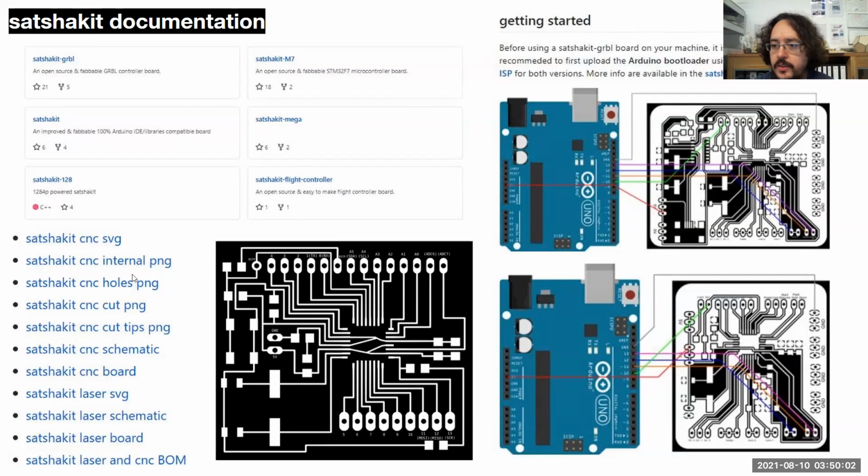But at that time, you know, there was just maybe the Eagle file. So what I brought was a complete pinout and the layout of the boards, the complete files, the complete instructions on how to connect things, and the step-by-step instructions on how to program them, how to use everything, and so on. So in this case, one of the difficulties we had was the conversion between the low-level pinouts, for example, the ports of the microcontroller, and the pinout of the Arduino bootloader, where you have, for example, the numbers of the Arduino libraries. And this always caused a lot of confusion.